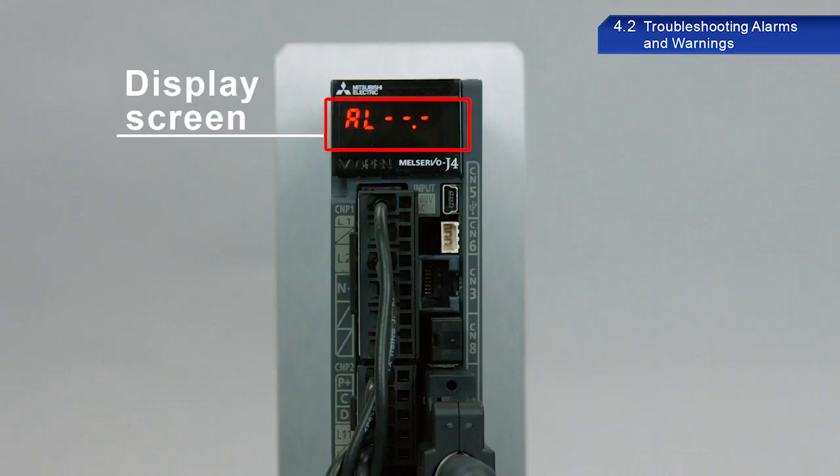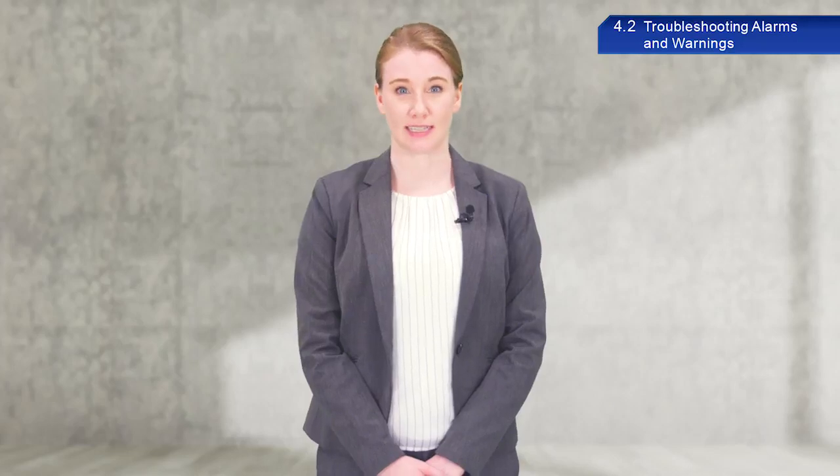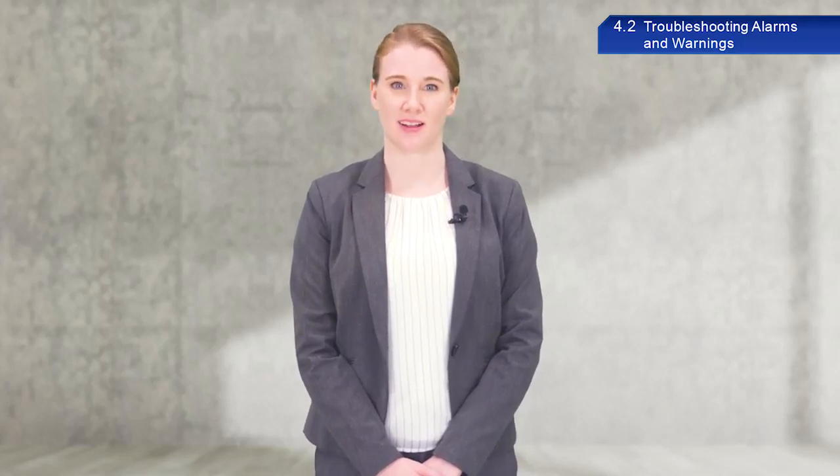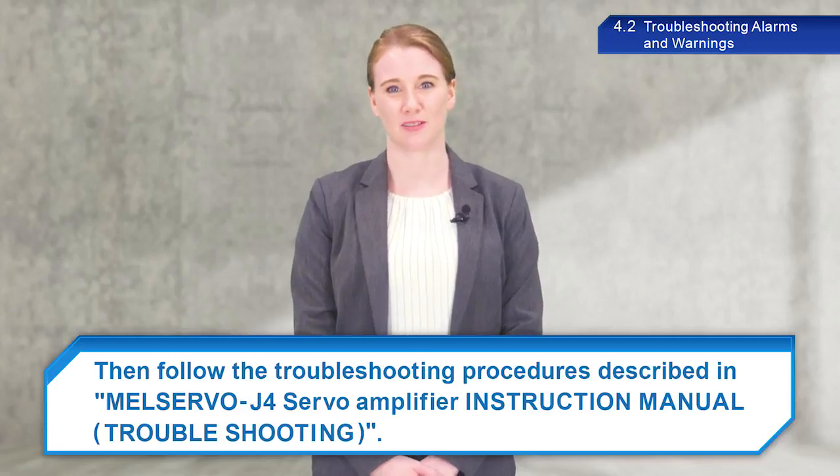Mitsubishi Electric servo amplifiers include a display screen for alarms and warnings when issues occur during operation. If an alarm or warning appears on the display screen, turn off the servo on signal and shut off the power. Then follow the troubleshooting procedures described in the manual.